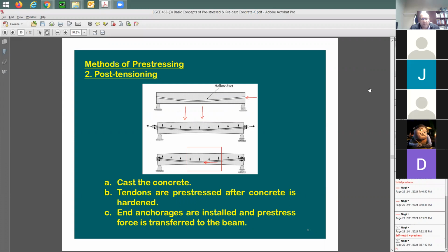Okay, good. So usually we try to match the deflected shape or deforming shape of the beam when it comes to putting the cable, just to be efficient. If you see here, if you put some loads, the deforming shape is going to look like this. So the best way is to put the cable very similar to the deforming shape. You don't put it opposite. Because imagine if you put this upside down, what's going to happen?